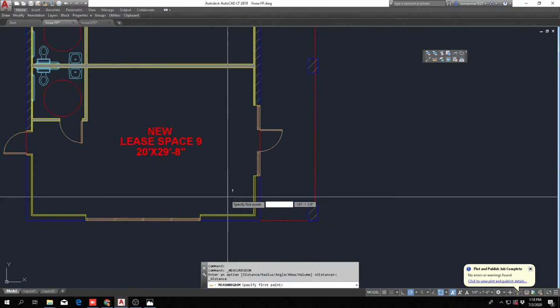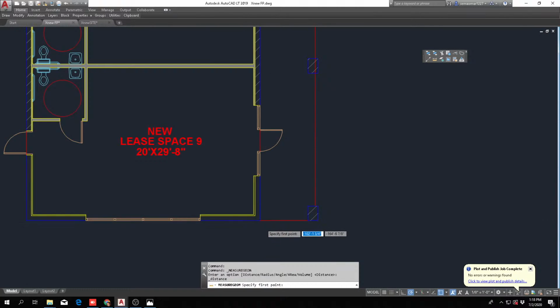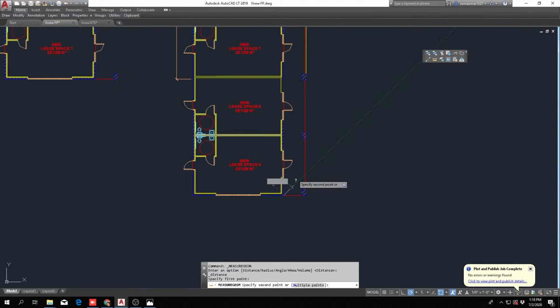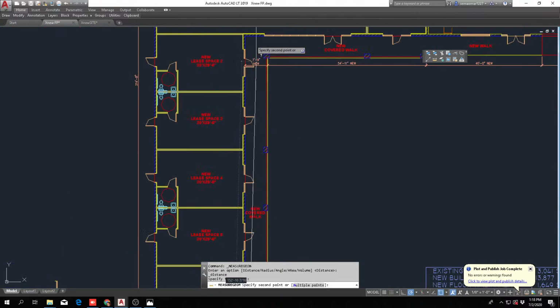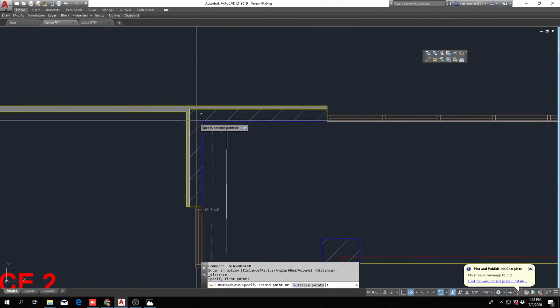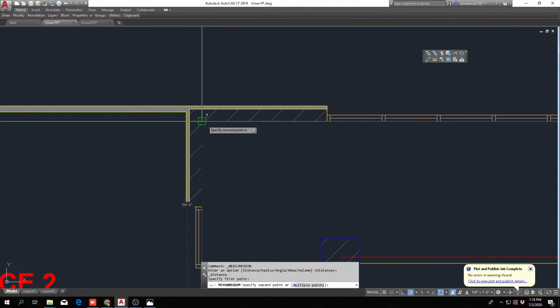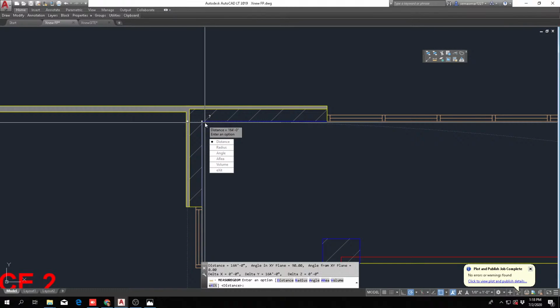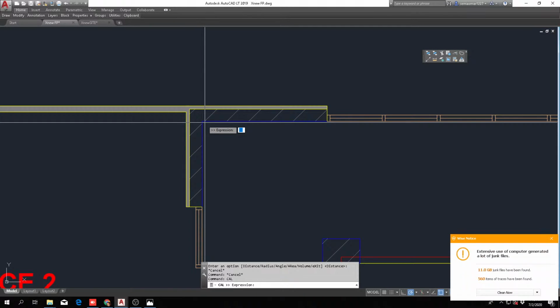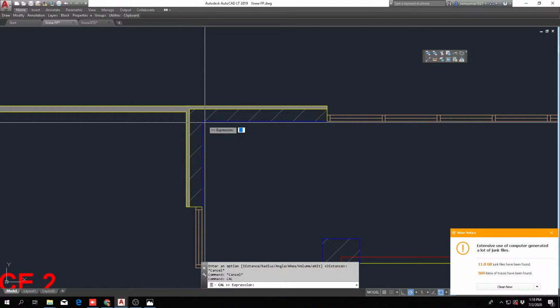And this might be a little bit wider. Why? Because like I said, I want to keep all these dimensions divisible by CMU blocks. So it's 164. And if you didn't know, you have a calculator here in your AutoCAD. All you need to do is put CAL, and that's for calculator.